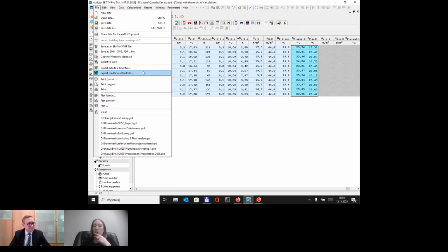Okay, we have another question. Rex asks, what would be a good delta T for radiant heating and for radiant cooling? For radiant heating, normally it's pretty low. It's between 5 and 15 degrees Celsius.